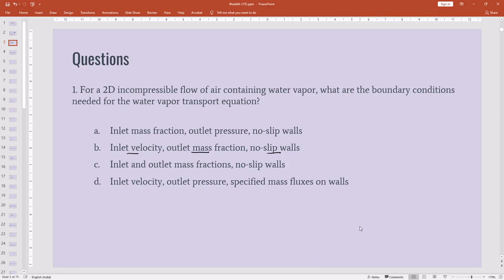Okay, here there is flow of air in our two-dimensional domain, and also water vapor is carried or transported through the airflow. So the boundary condition should account for both of these. If it was flow of air, what would be the ideal boundary conditions for a two-dimensional domain? We want to simulate an airflow in a two-dimensional domain.